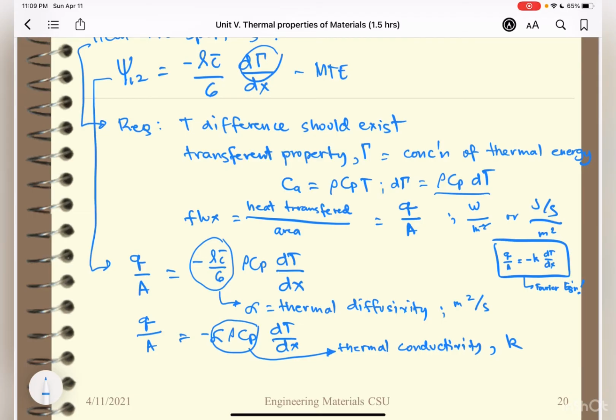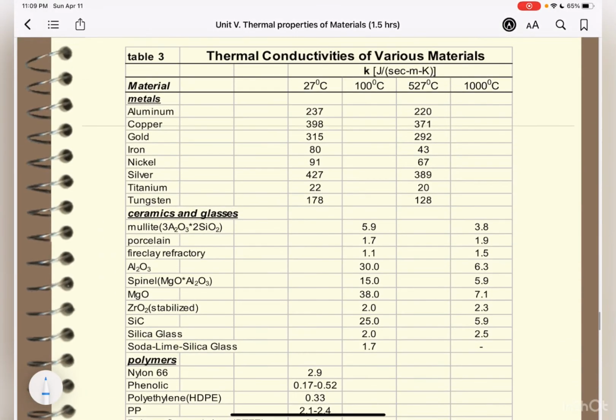Okay, so I have here the table of the different conductivities of various materials. Of course, in ceramics, take note of the K. At 100 degrees, these are the values, quite small. Of course, very high for metals. Porosity in ceramic materials may have a dramatic influence on thermal conductivity. That is, increasing the pore volume will, under most circumstances, result in a reduction of thermal conductivity.